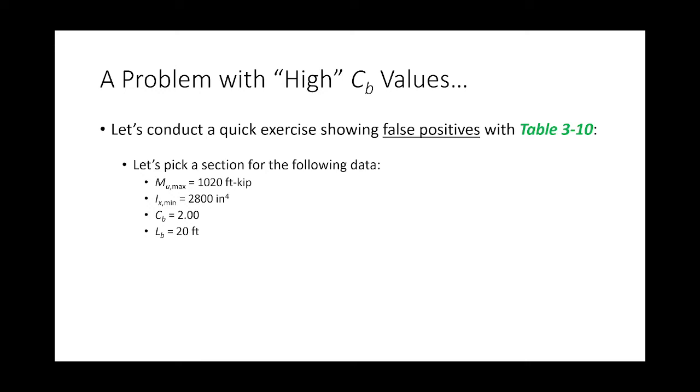No. What I do is I go into table 310 with an LB of 20 feet, but the MU value we go in with is our moment, but we divide out our CB value. So we get an MU over CB of 510.